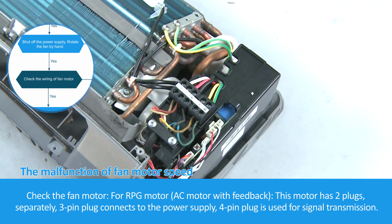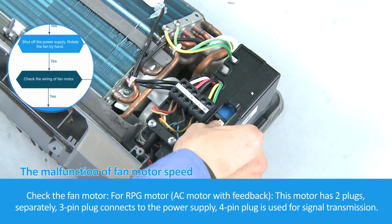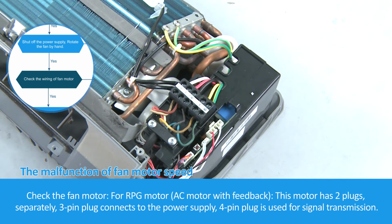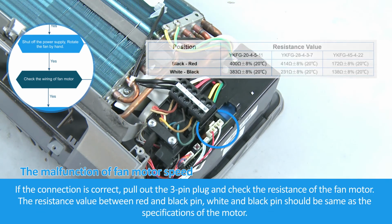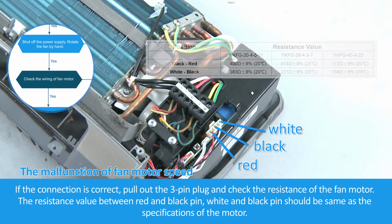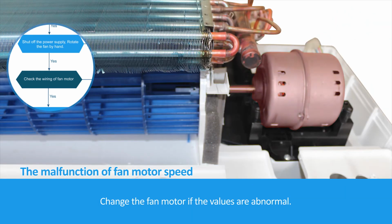This motor has 2 plugs, separately. The 3-pin plug connects to the power supply. The 4-pin plug is used for signal transmission. If the connection is correct, pull out the 3-pin plug and check the resistance of the fan motor. The resistance value between red and black pin, white and black pin should be the same as the specifications of the motor. Change the fan motor if the values are abnormal.